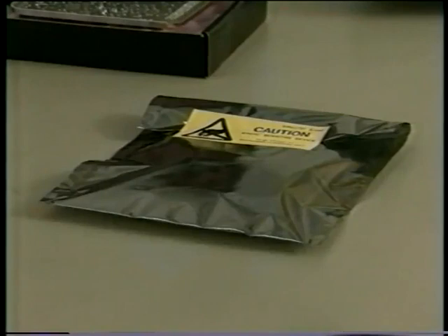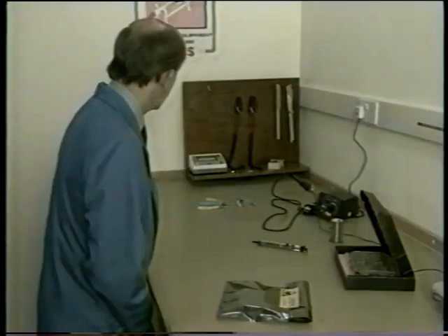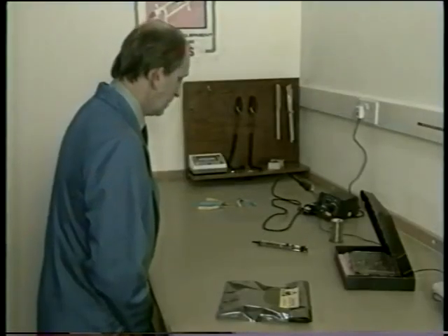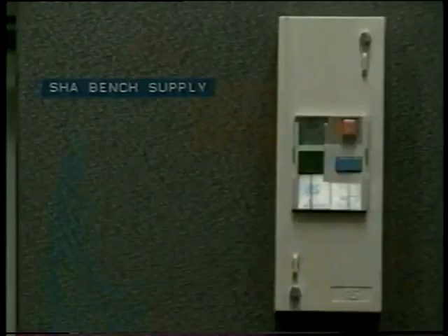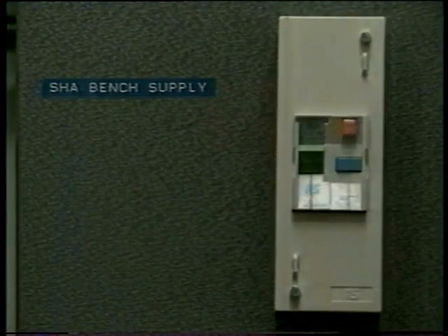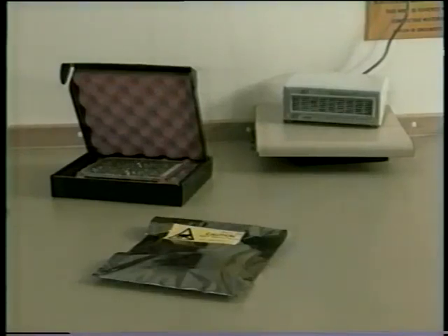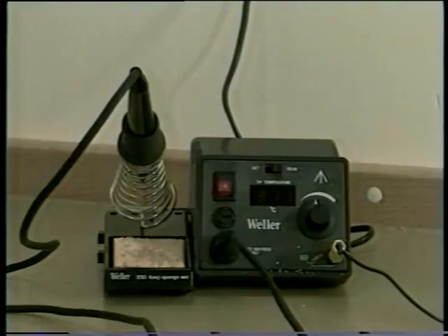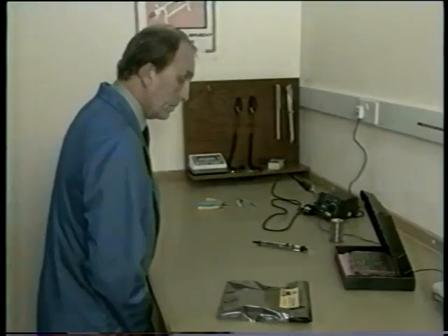All vulnerable items are specially packaged and should only be opened on the bench, so that everything is at ground potential. A Type 1 special handling area has mains power provided to it via a residual current device. Any bench lighting or soldering irons used should derive power from this source. The bench is used for the full range of tasks, such as component replacement, module rework, or programming of memory devices.